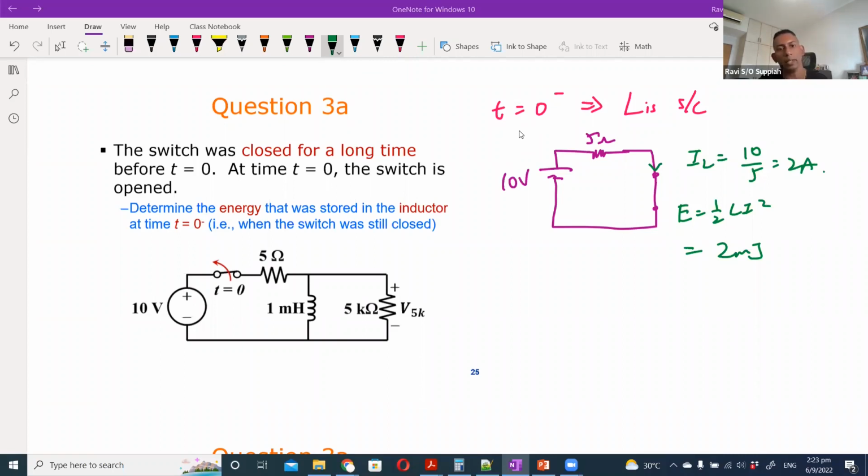You will need to do that if your capacitor's charging or discharging is through some network of resistors. The time constant, RC or L by R, is based on a single resistor. But if you have multiple resistors connected, then it is equivalent to looking at it from a Thevenin's equivalent to know the effective resistance that you are discharging your capacitor or inductor through.